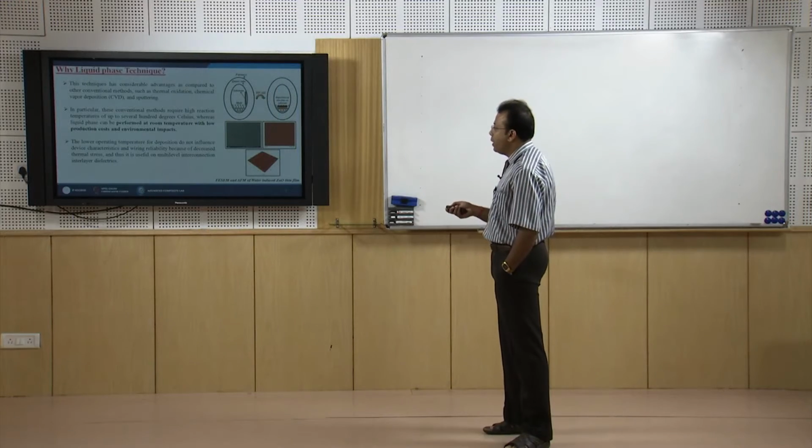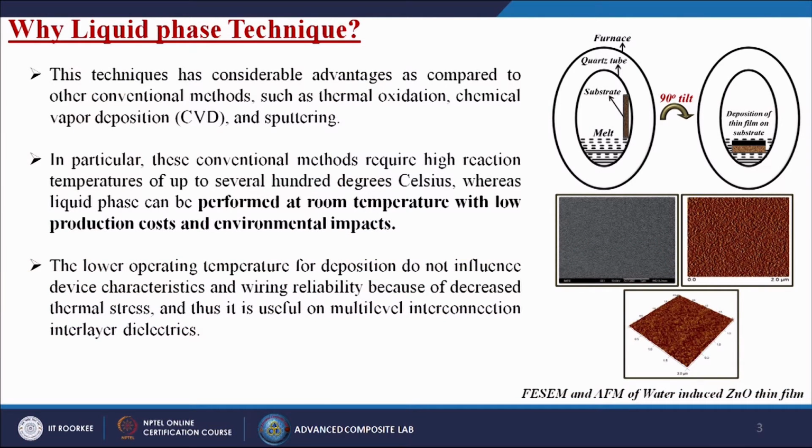The lower operating temperature for deposition does not influence device characteristics and wiring reliability because of decreased thermal stress, and thus it is useful for multi-level interconnection interlayer dielectrics.